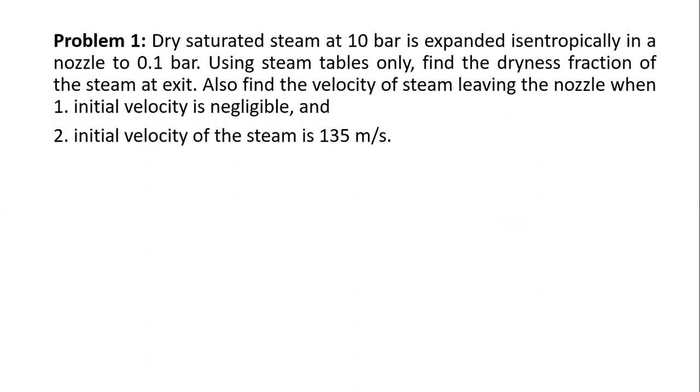Question: dry saturated steam at 10 bar is expanded isentropically in a nozzle to 0.1 bar. Using steam tables only, find the dryness fraction of the steam at exit. Also, find the velocity of steam leaving the nozzle when